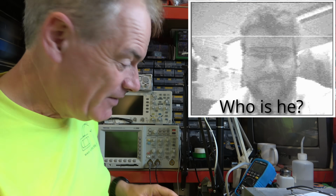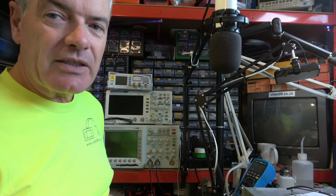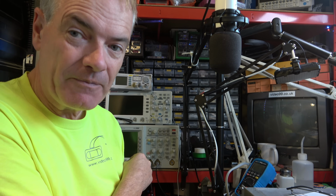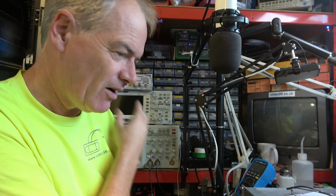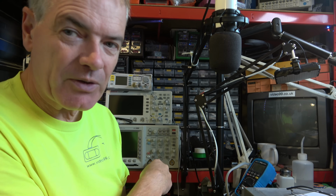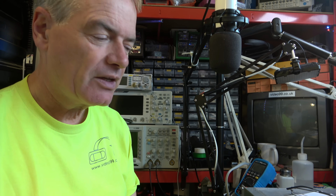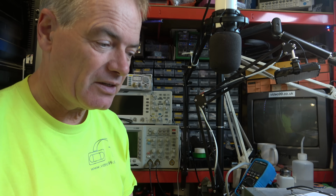And anyway, even as a vectorscope, it insists on 2 channels. So you could only use this in a situation where you have a component output. For composite video, you can display the image sort of on the screen, but there's no chroma decoder in there, no color burst decoder, it can't do true color decoding, which is why you can't feed it with composite video and expect it to work as a real vectorscope like the ones I have in the studio. So as a vectorscope it doesn't really work, I don't think. In my humble opinion, it's not terribly successful.